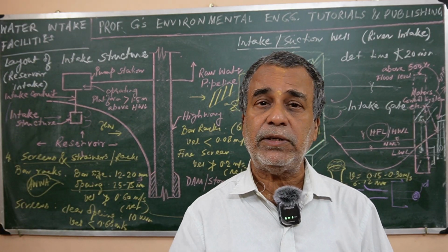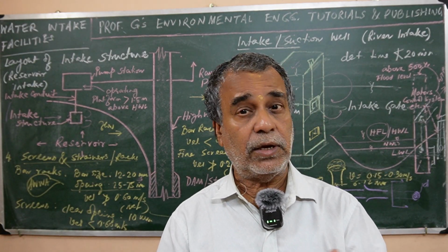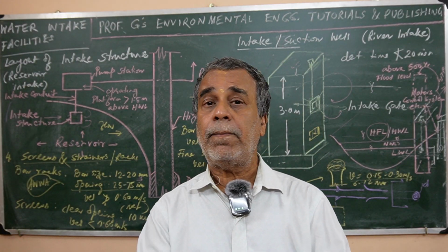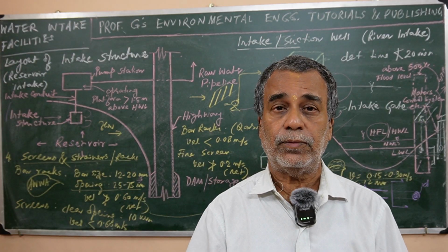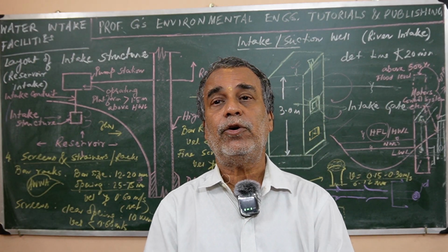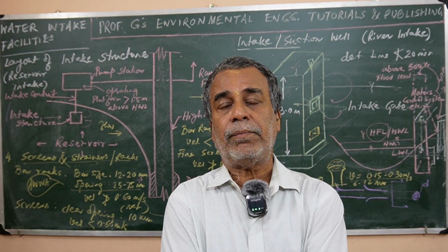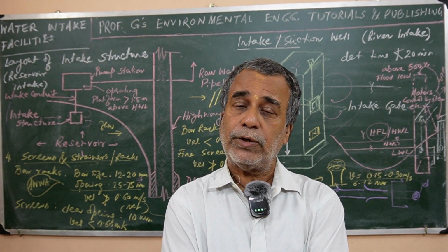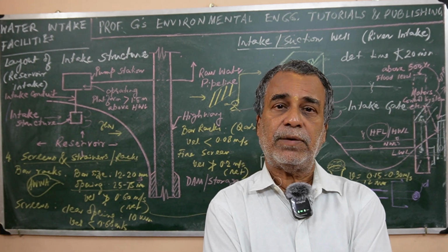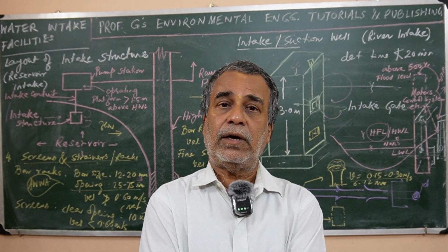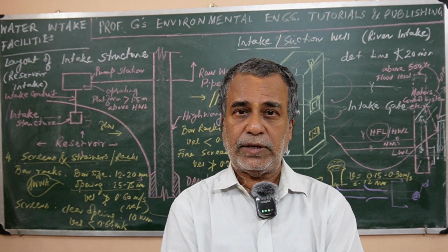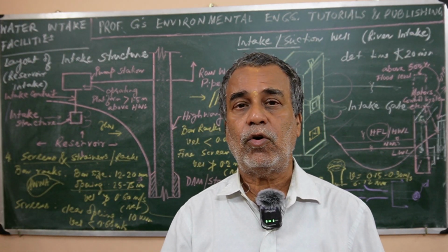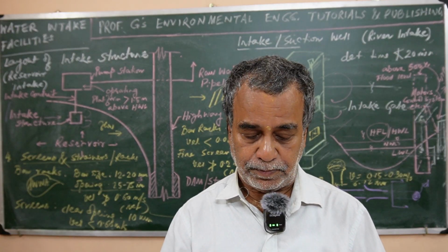And unwanted materials may enter, because it is placed, as I have told, I repeat it here, just before the pumping. So it must be properly placed and properly designed, otherwise the entire pumping system, particularly the pump operation, will be very much affected, requiring very frequent overhauling or maintenance.